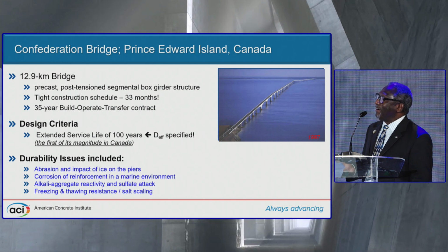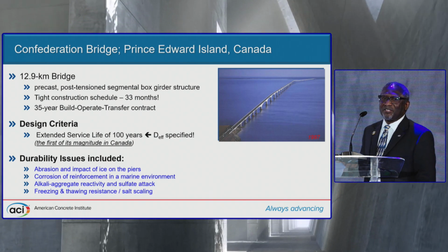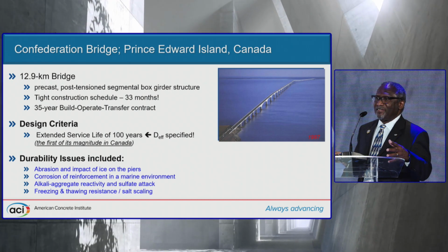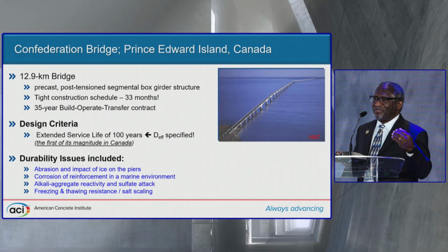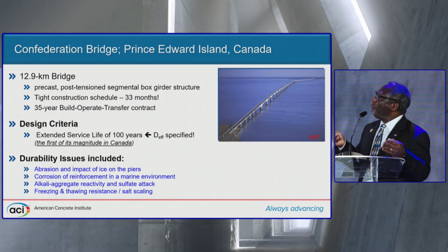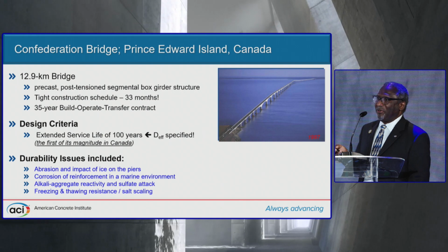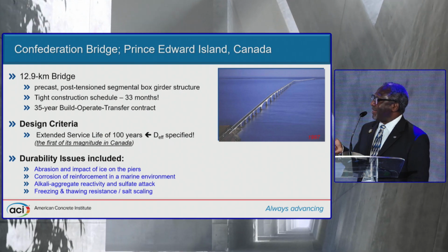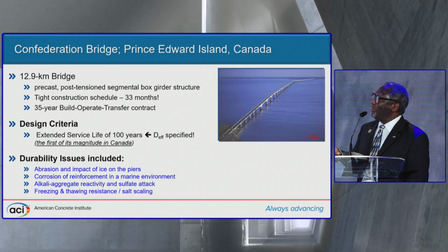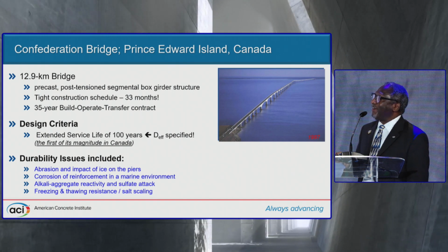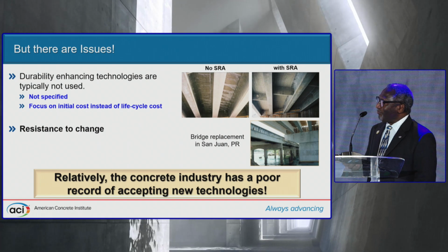And then, being in Canada, freezing and thawing resistance, as well as scaling resistance. So these were all the things that the design engineers considered during the design of this particular bridge, and there were parameters set to make sure the durability will not be compromised over the desired service life of the concrete.